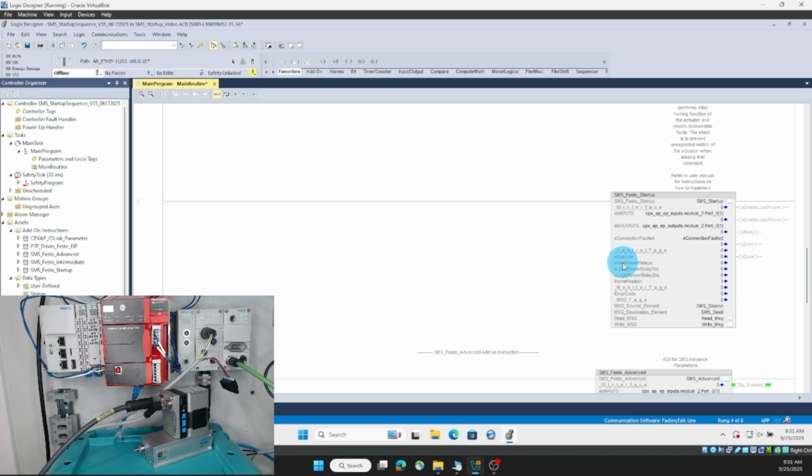So it takes care of the execute bit. Use power relays. In this hardware example, I'm doing the most simplified approach, which is not using external relays to toggle the load and logic power on. Based on our manual, it defines that the load power should be turned on after the logic power by 50 milliseconds. So this provides the functionality that if you set this use power relays to 1, that it will drive some relay statuses or relay commands to then turn on external relays.